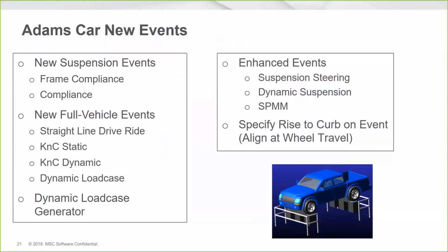The dynamic load case event is an event that actuates the assembly at the wheel center using user-defined function expressions, or can reference a channel number from an RPC3 file. And here you can do two types of analyses, either force-based or displacement-based. For the steering input, it's also possible to define a runtime function expression or reference a channel number from an RPC3 file as well, to define the steering motion. So you can combine vertical excitation and steering sweeps.